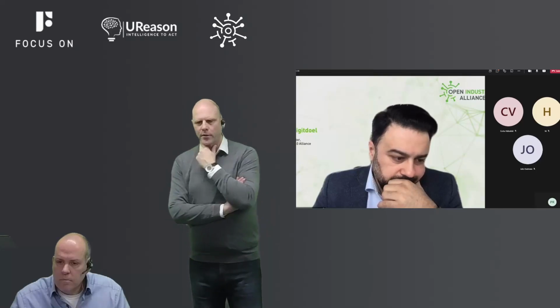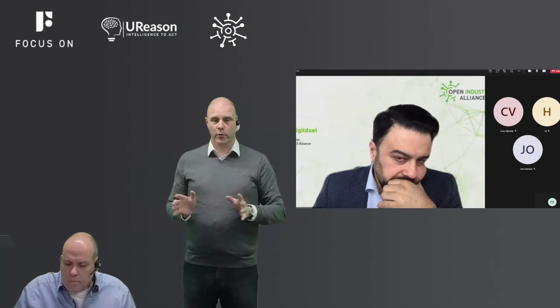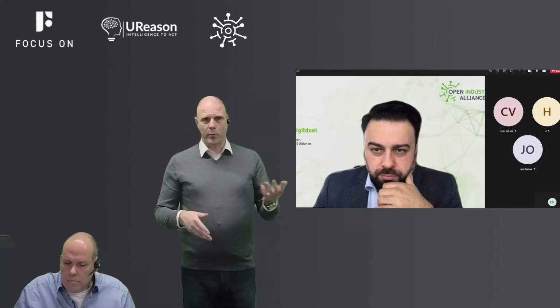Yep. So I hope my mic is on so that people can hear me as well. For Eelco, by Torsten: what's the required straight pipe length for up or downstream? Yeah, good question. It remains a field instrument, so we have some requirements there. By the way, we communicated all the fancy protocols, OPC UA, MQTT, etc., but it can still operate with 4 to 20 milliamps HART. It has an input, it has an output. We can communicate also at a very basic level within your process.